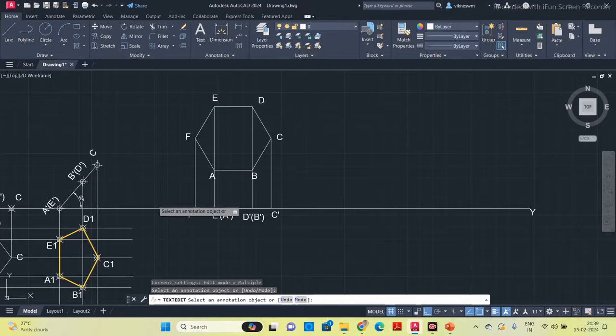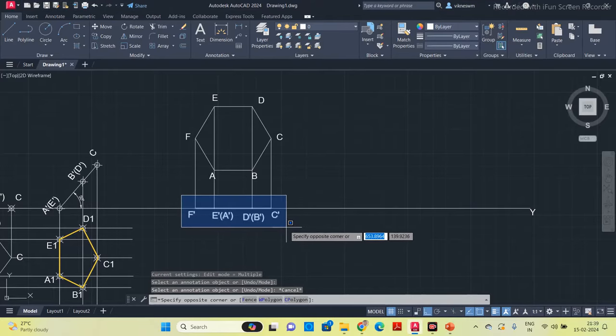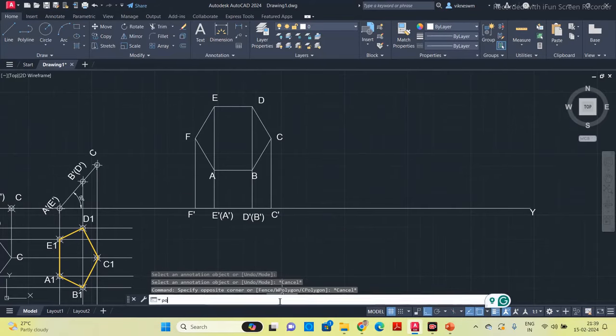So you select all 3 lines along with the letters. Before this, we put a point on each corner so we can identify these corners in the top view. Now select all the lines, letters and corner points.